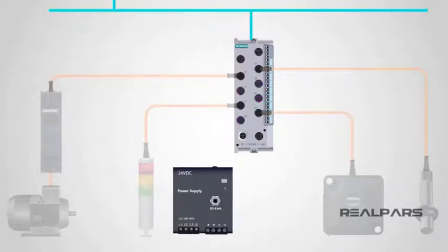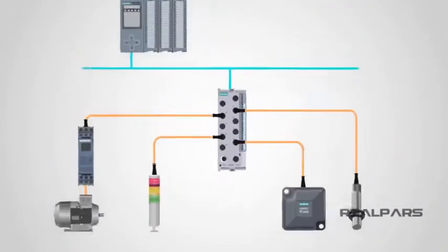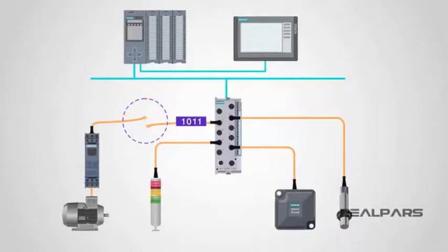I/O link is a very robust communication system that operates using 24 volts. Transmission errors can occur for a number of reasons. In general, a cable fault or a power surge can temporarily interfere with transmissions. If an error is detected, the message attempts transmission up to an additional 2 times. Only after the transmission has failed for a 3rd time does the I/O link master recognize a communication failure.